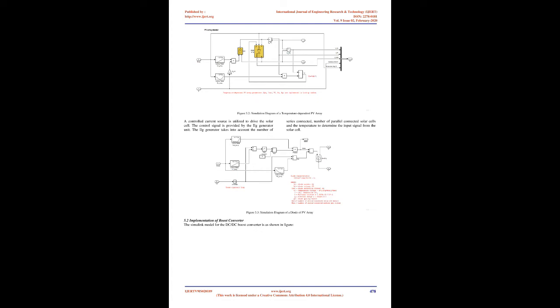3.1 Methods of MPPT. The MPPT methods can be categorized as direct or indirect. The indirect methods can also be classified as quasi-seeking, since there is no actual seeking, but only approximation by some other method. Direct methods use measurements of the photovoltaic voltage, VPV, and current, IPV, and obtain the operating point by changing the voltage based on their response to obtain the MPP.